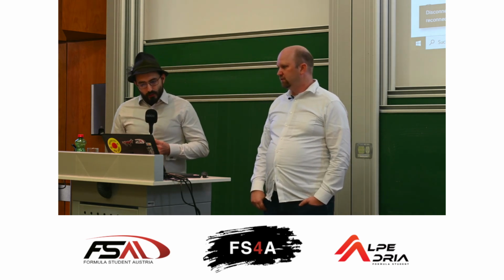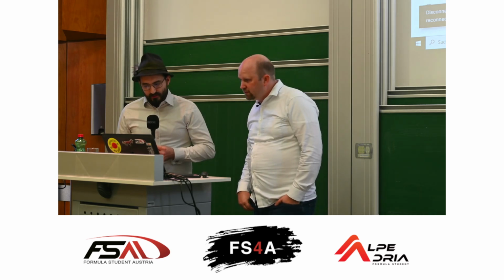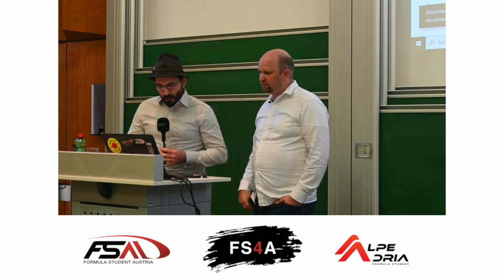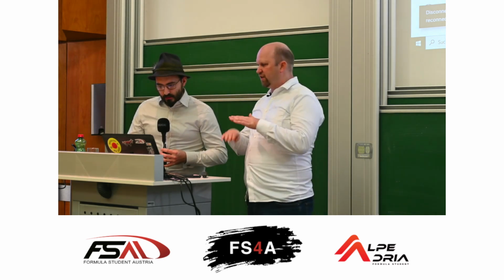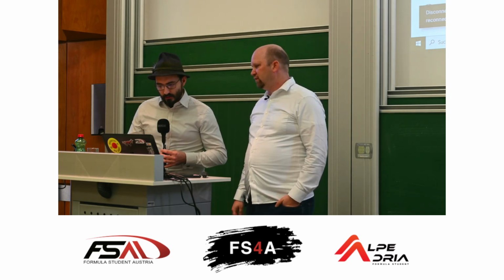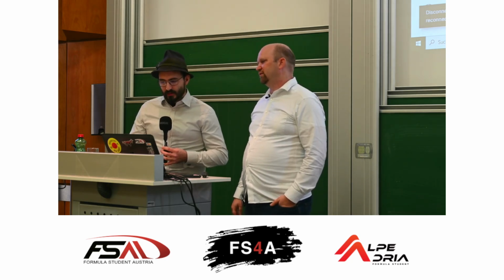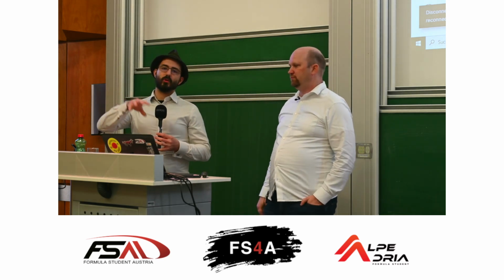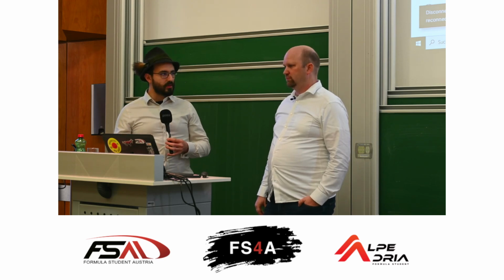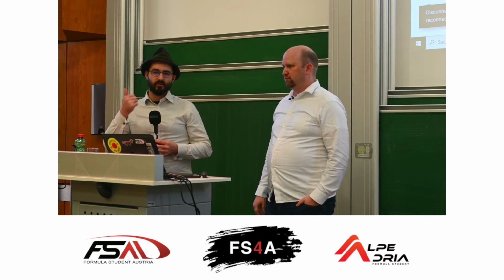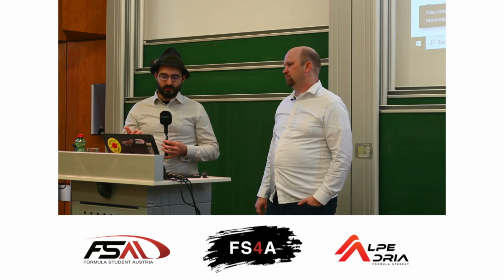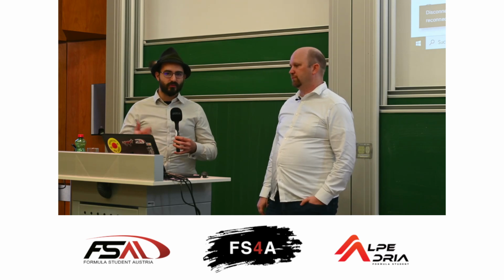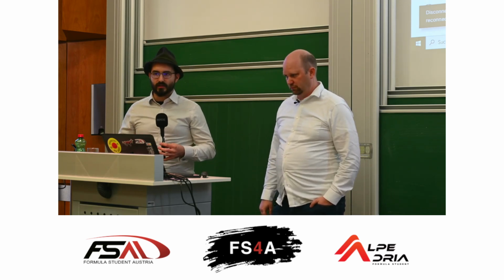EV 3.1.1. Can the accumulator be constructed of multiple different materials? So this is basically the same question as before. Yes, but the rule EV 3.1.1 says you can either make your whole accumulator out of non-conductive materials. Typically this would be a laminate out of glass fibers or aramid fibers. In that case, everything is non-conductive, and if there is some kind of shortcut, everything is isolating, so there is no issue.